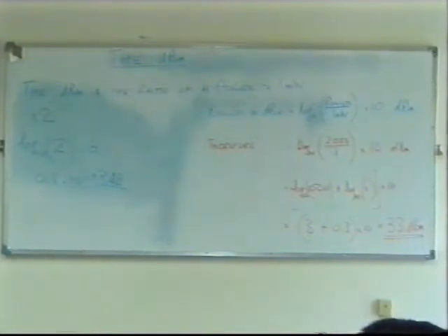Notice only a 3 dB change, that's all. Just 3 dBs difference between the two. But he's not going to tell you that. He's going to say, this, in big writing, is a 100-watt amplifier, whereas this little thing is only 50 watts. And there'll be a big difference in price too. But you're only getting 3 dBs difference.